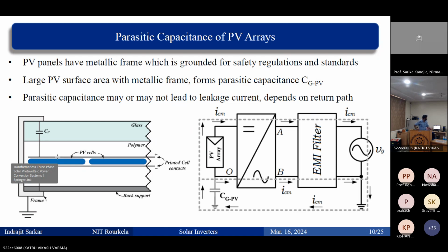So the purpose of saying this is, that capacitance exists everywhere. Somewhere it is very low, so negligible, but it exists when there is a potential difference. Let's say there is a conductor, and I am standing below it. The conductor is carrying some potential and there is a ground potential. There is a difference between these two potentials, and there is a dielectric, the air.